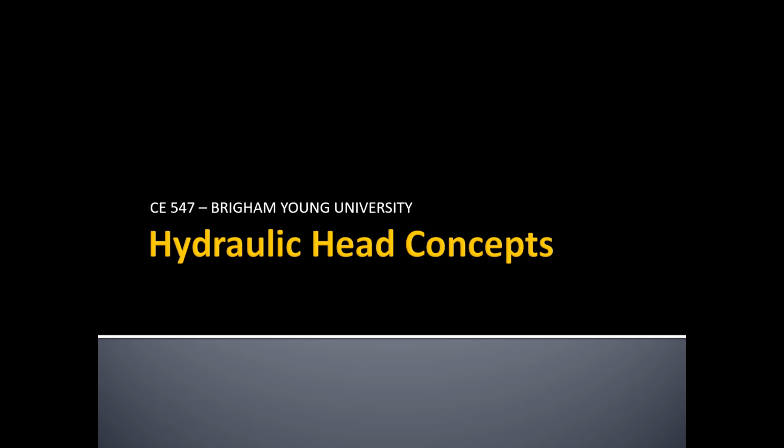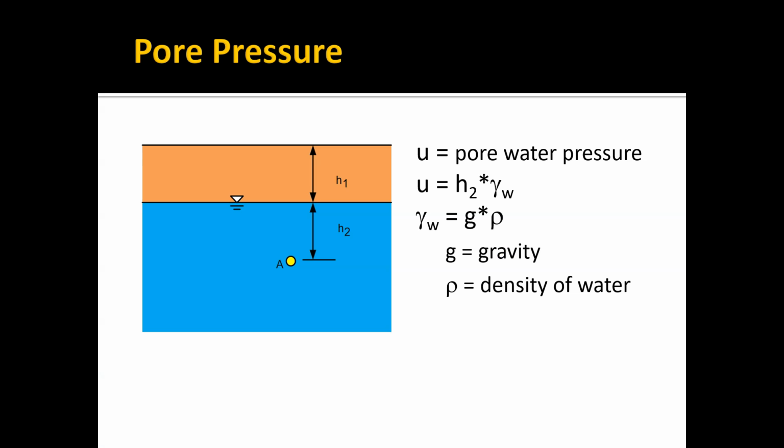We're going to rederive the primary equation associated with this, and then discuss a few examples to illustrate what it means. And then, of course, in class, we'll do some exercises associated with this. So, what is hydraulic head? Before we get to that, we want to review a concept called pore pressure, or pore water pressure. That is when you have saturated soil or rock where the water fills up the pore space in the soil or rock. The pressure of the water in those pores we call pore pressure.